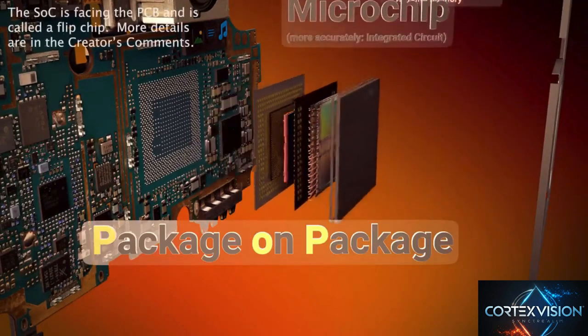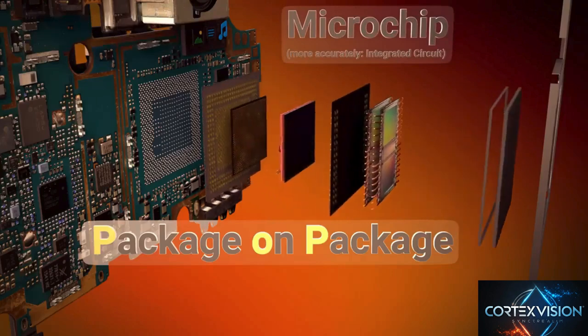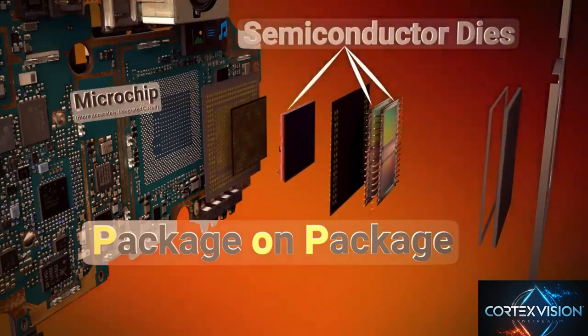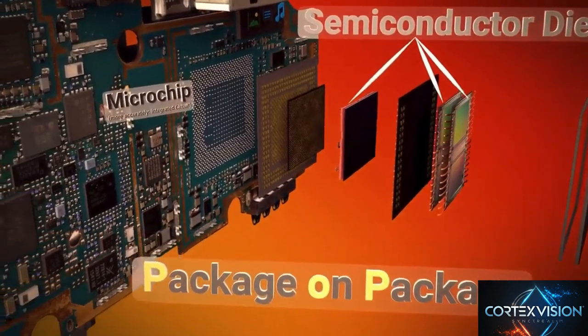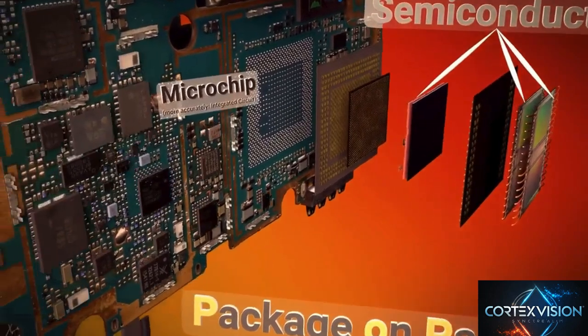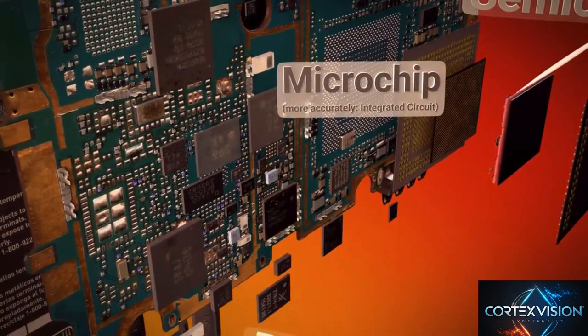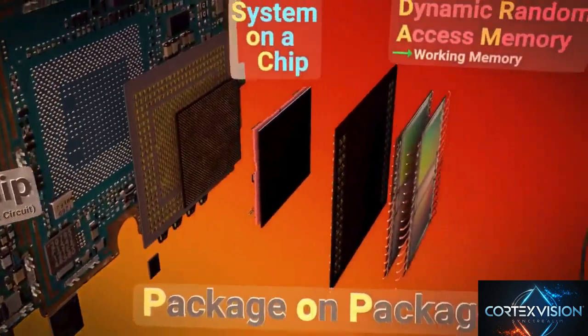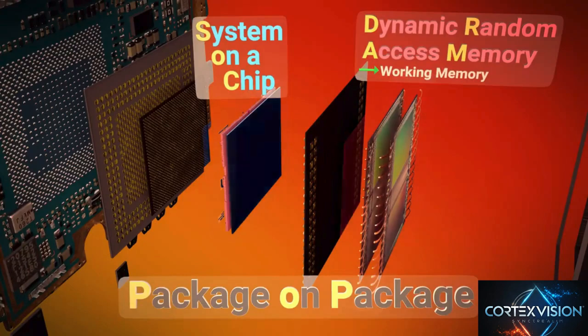Technically, this is the microchip, and the separate layers of the DRAM and SoC are each called a die. However, the word chip has evolved to mean a variety of things. So, while all of these rectangular components are microchips or chips, both the DRAM and system on a chip are also called chips, even though they're just half of the overall package-on-package microchip.